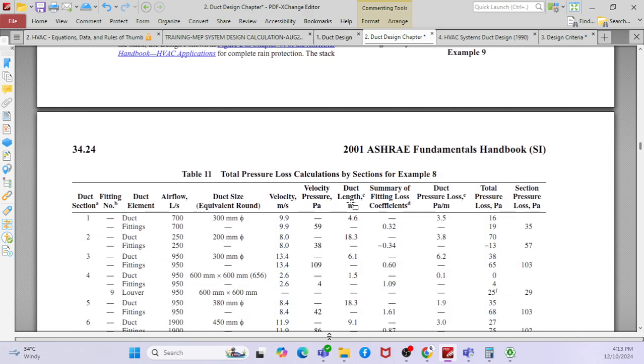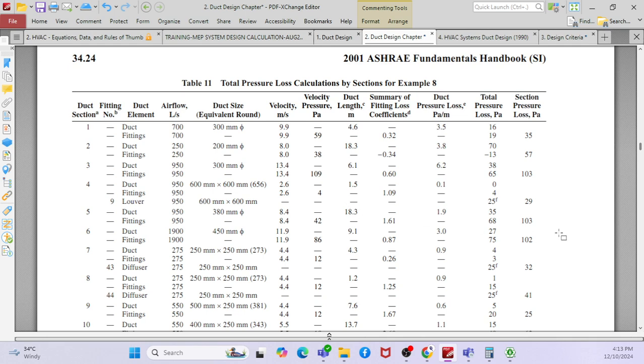Can I ask you something, Pranny? Yeah, tell me. You said we have the absolute roughness factor, which we use for different types of ductwork material. Correct? Yeah. So my question is, generally for projects, say we use carbon steel or normal GI, galvanized iron, right? Galvanized iron. Exactly. You have different materials and different roughness factors. So whatever type of material we are using, we can apply that roughness factor.